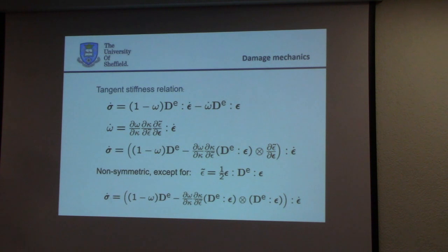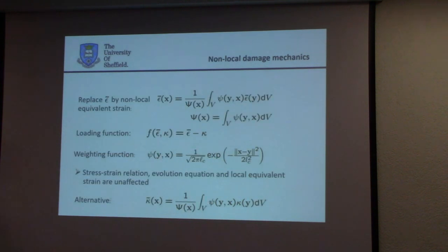So to solve that, we can say, okay, we don't make the stress in a point depend on the strain and the strain history in that point only, but we also make it dependent on a finite neighborhood.